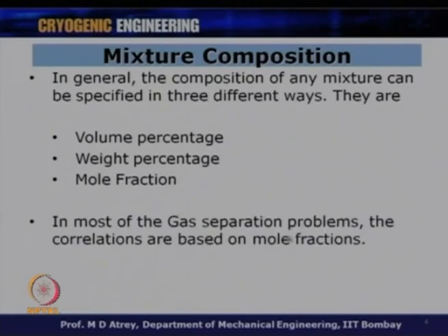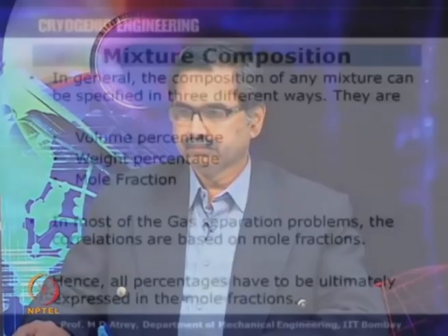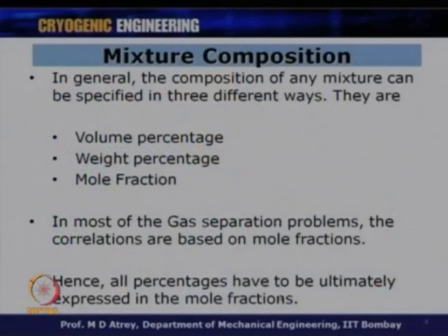In most of the gas separation problems, the correlations are based on mole fractions. So, if the fraction is given in mole fraction, absolutely all right. However, if they are given in weight percentage or weight composition or volume percentage, we will have to first convert this composition from volume or weight to mole fraction and then utilize the mixture rules and things like that. So, first we would like to understand what these mole fractions are all about. Hence, all percentages have to be ultimately expressed in mole fractions.